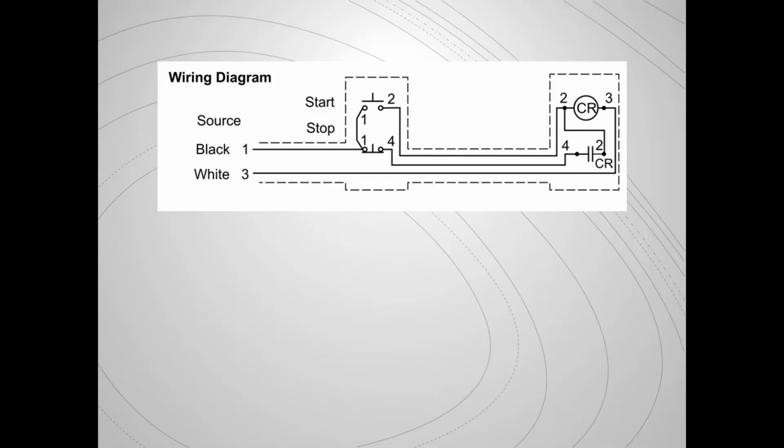Wiring diagrams are great for installation purposes, but when it comes to troubleshooting and understanding what is happening within that circuit, the schematic diagram is really where we should be looking. Whenever we have either a wiring diagram or even a piece of equipment in the field, we can take the information that we can find within that and create our own schematic diagram. The most important aspect to this is to make sure that you are organized.